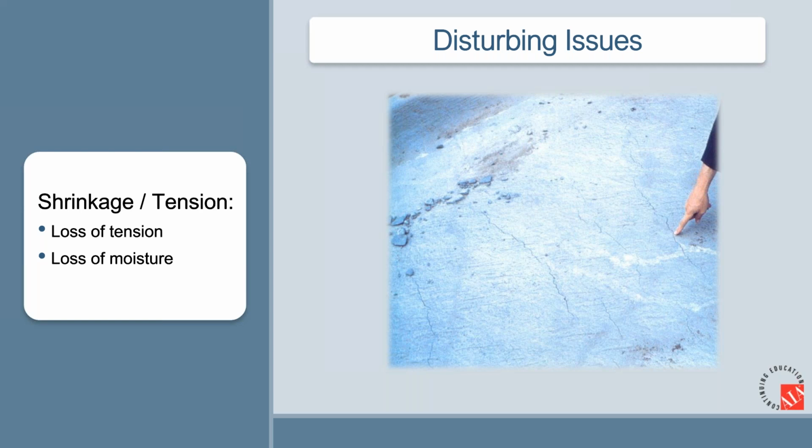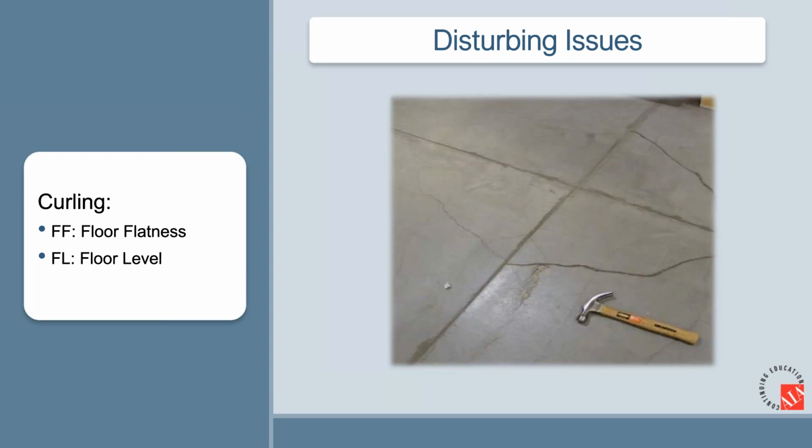All of your sidewalks have joints. All of the joints are laterally placed along the longitudinal axis because it moves back and forth along its long run. If we understand that behavior, it helps us design and place concrete properly to avoid these situations. Putting the joints in right and controlling the loss of moisture will prevent cracking from taking place, both in the curing and in the drying phase, if we understand the behavior.